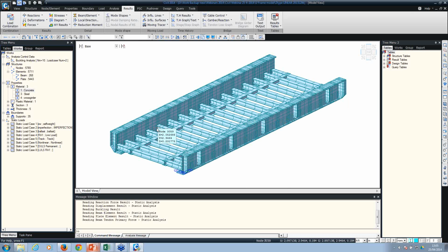But that may make the bridge a low rating bridge. But when you do a full detailed assessment analysis on an FE model, you can actually see that all these cross girders which do not have a stiffener also participate in the U-frame action, and they're sufficient to resist the lateral torsional buckling. So let me show you how the buckling checks were done on this particular bridge.